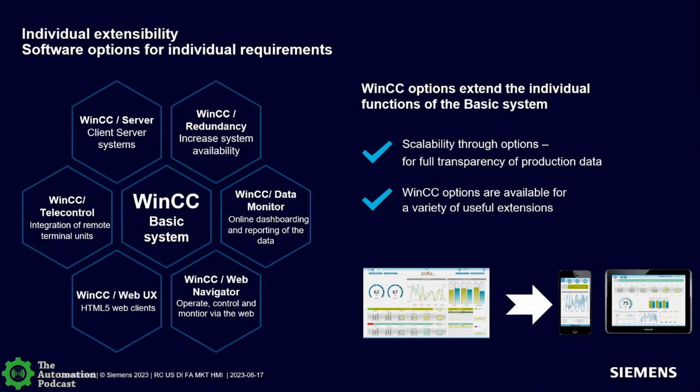So you have the Microsoft server operating system you need, but you also need the WinCC server option so that you can do the client server network. Redundancy gives you the ability to secure your system availability, whether you want to make sure that you don't have any downtime, or you want to make sure you have critical data backed up. You can do a redundant pair, 3 redundant servers, 4 redundant servers, whatever you need.